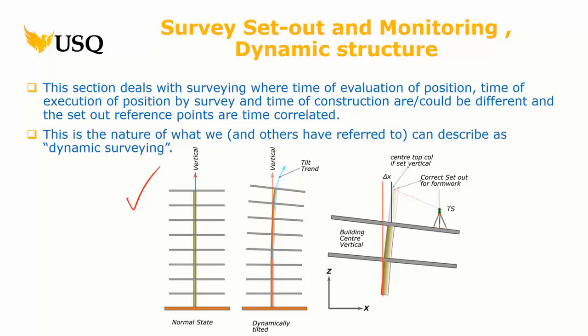Dynamic surveying says that you're actually holding the tripod with a total station on top, and you're moving, and you're going to be reading everything at the same time. That puts it into a new focus. Number one, it makes it really hard to level the instrument while you're moving. So you see how it goes completely out of the way we think about things. It's a leap, not quite as big as going from traditional surveying to GNSS, but it's a leap all the same.